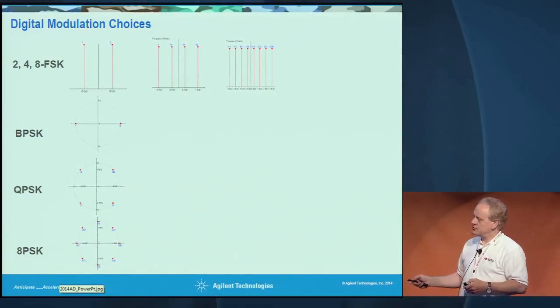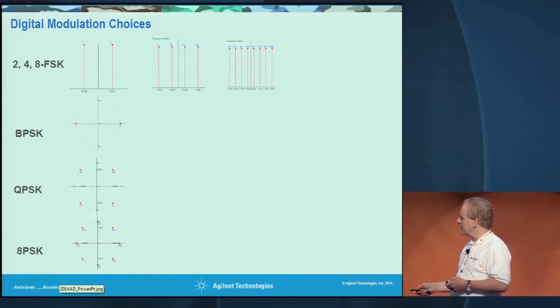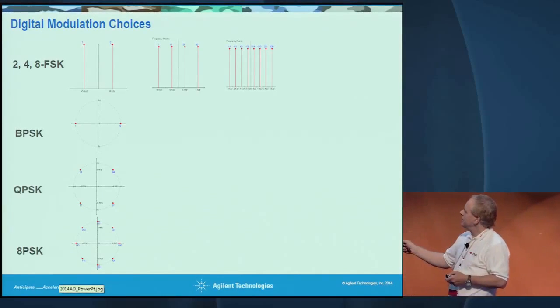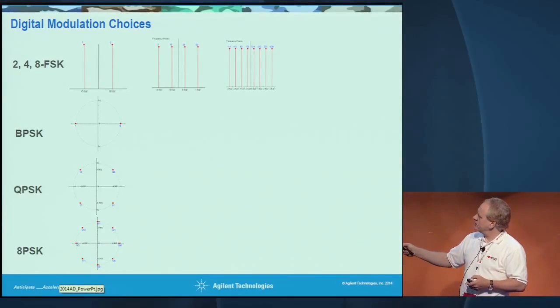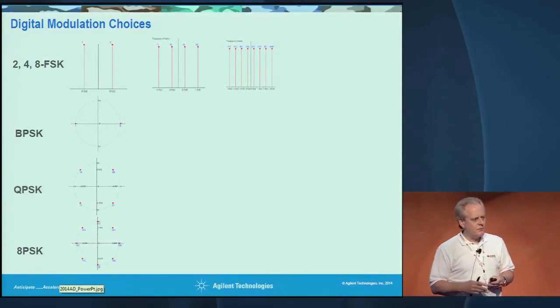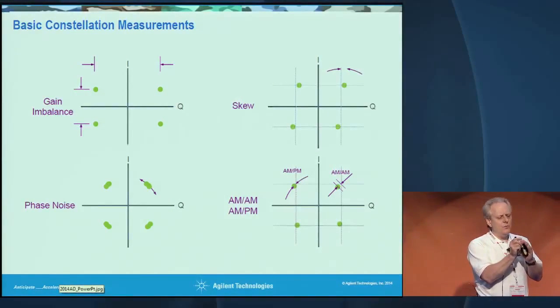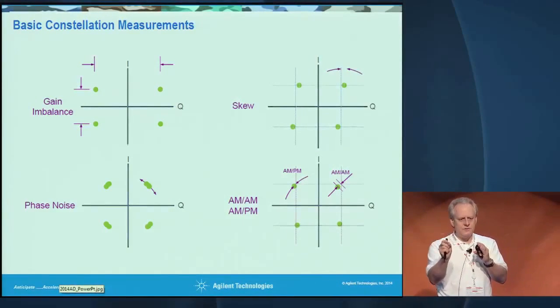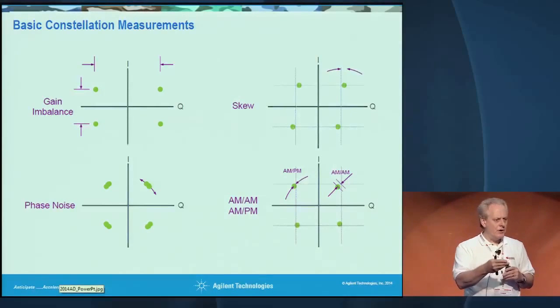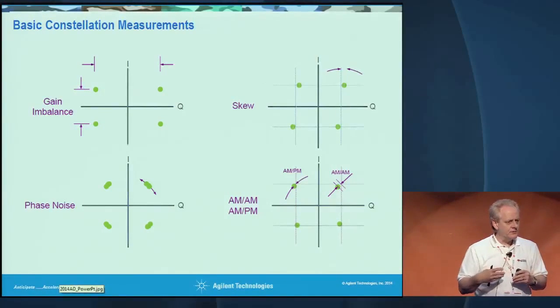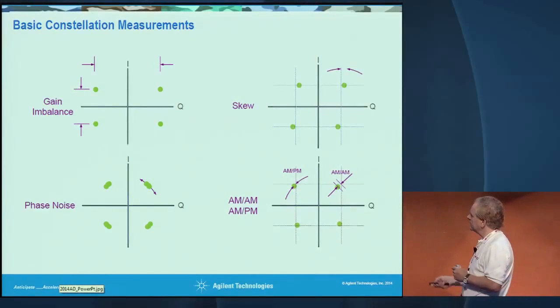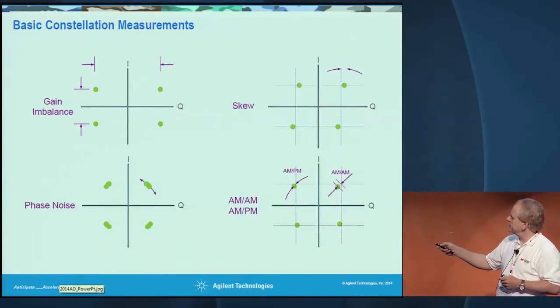Now in these formats, you have additional challenges with measurement quality. So before, when you're just hopping frequencies, frequency shift keying, or using simple modulation formats, you care a little bit less about some of these things. As you pack these modulation rings tighter, you begin to need to worry about how far each of these states is from each other. So noise and nonlinearities and different things affect the quality of the states. So some of the things that can go wrong that you'll want to measure are